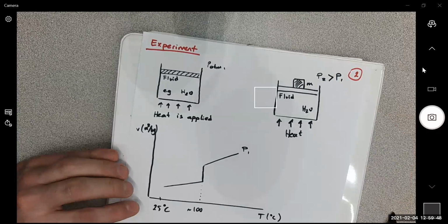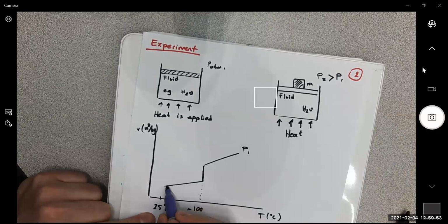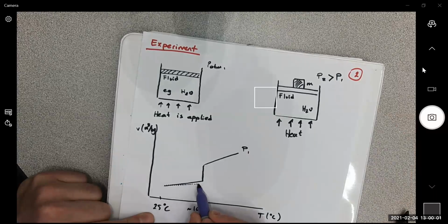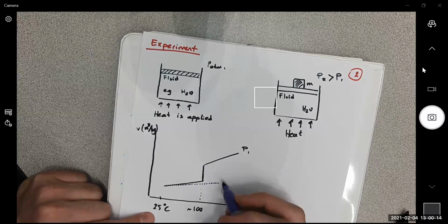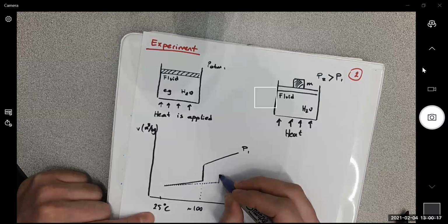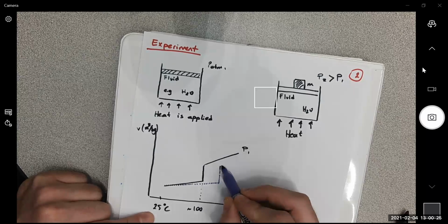What happens in that case is that it starts increasing temperature and specific volume. But this time around, my saturation temperature, meaning boiling temperature, is different, right? It's higher because my pressure is higher, and after boiling starts, constant temperature because of phase change. Same thing happens here.